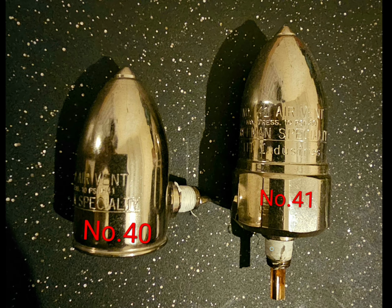Likewise, when it comes down to certain Hoffman air vents, the 3/4 inch opening, they got Hoffman air vents with a 3/4 inch opening. I think I might have one somewhere kicking around in this apartment where I'm at now. But just based off of, when you look at this bead over here that has the hexagon fitting, this is made out of a thicker brass. And if you have a 3/4 inch opening with thicker threads, that's even that much more brass that can hold heat. And we all know the thicker the metal, the better the metal is going to hold its heat.